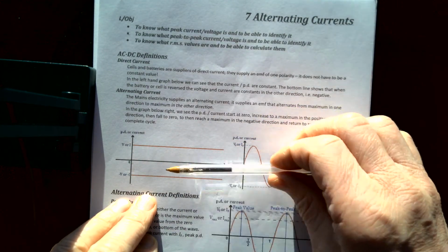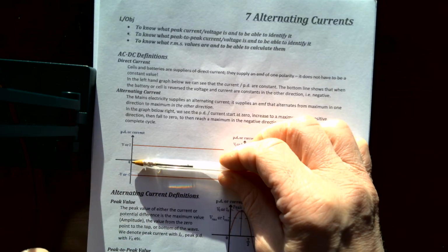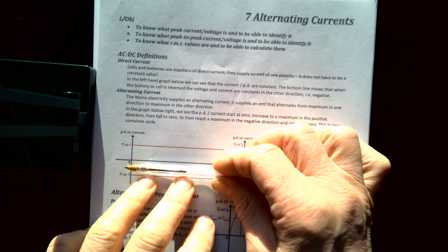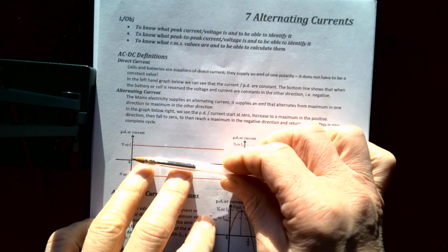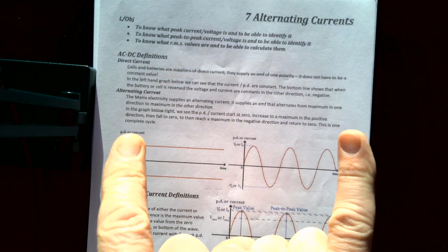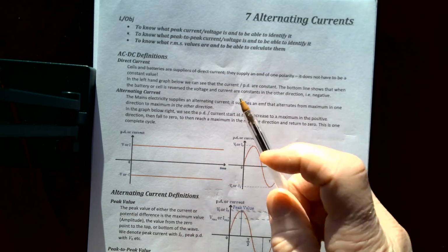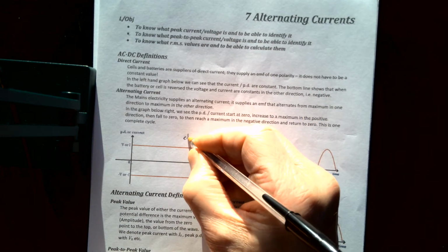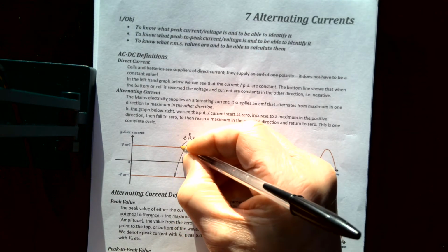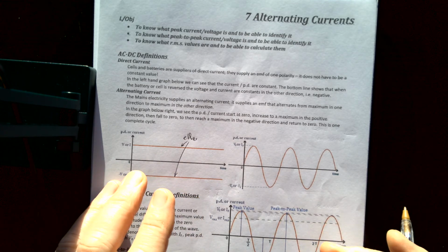If you turn off your input, it always goes to 0, obviously, because you've got no input, and you adjust it to a convenient square on your screen, and then it will jump up when you turn it back on if you've got a constant voltage. If you connect your voltage the other way around, it will jump down by the same amount. So it will give you either of those, all depending on which way you connect your battery to the oscilloscope.